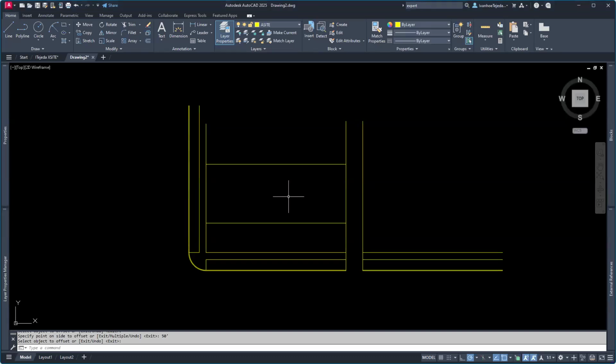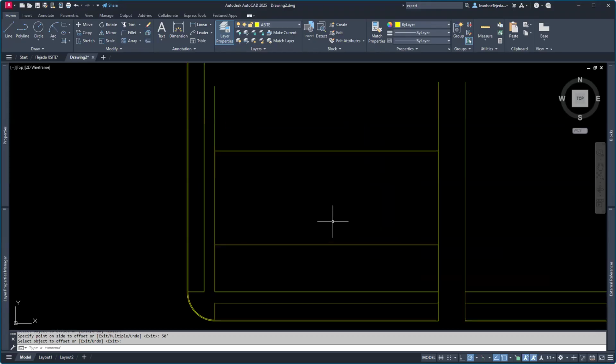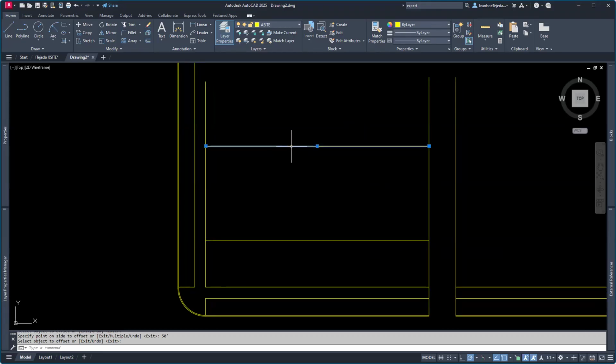So now what I'd like to do is start to get my property lines in there because I think everything is good. And then I'll come back and put in the buildings. But I want to touch on the property lines. So this line here and this one, I'm selecting them. I want them to be on the property line. So with them selected, I go to my drop down here and I say a site property. Great. And they are now that magenta color.